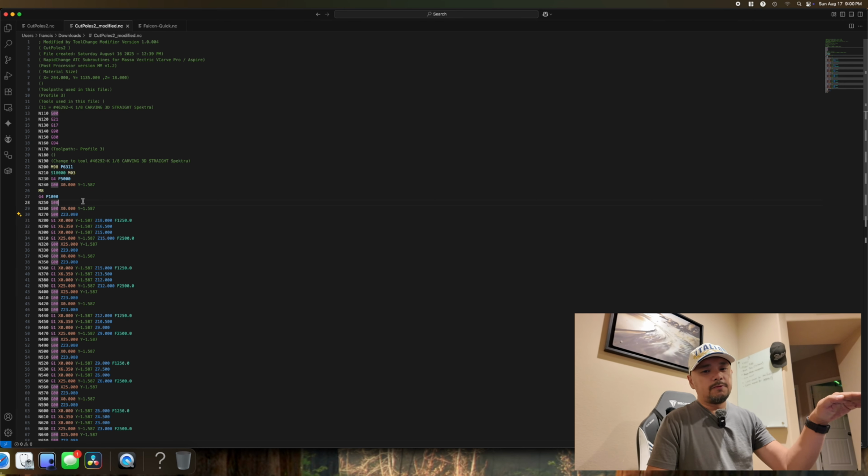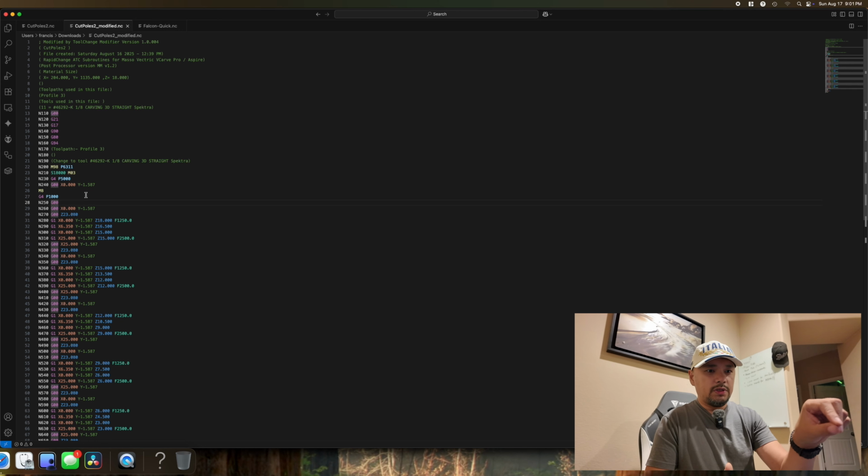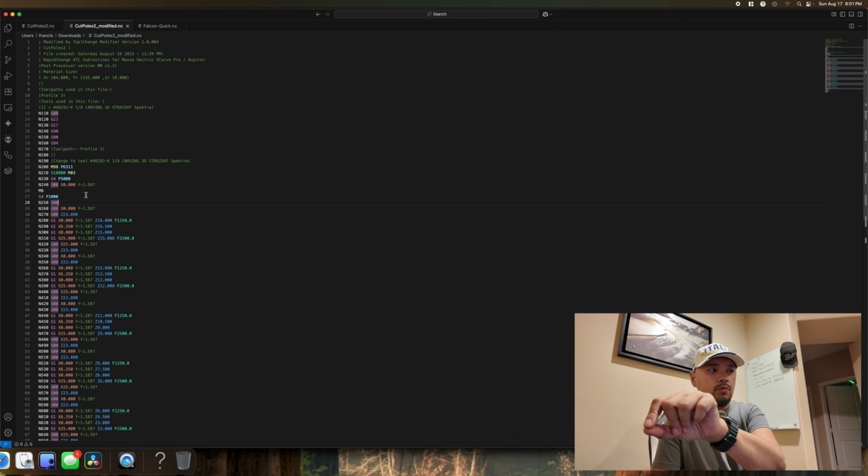So what will happen is, after the last part of the tool change, it does the tool measurement. Now if you followed the suggestion of putting a move away in the after tool change, that will also be executed. And then after that, the spindle will move to the XY location to continue the job.